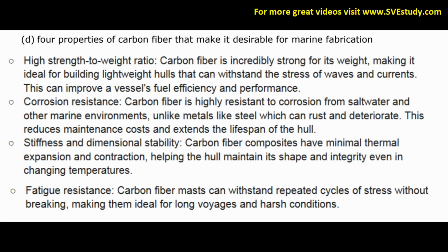D. 4 properties of carbon fiber that make it desirable for marine fabrication. 1. High strength to weight ratio. Carbon fibre is incredibly strong for its weight, making it ideal for building lightweight hulls that can withstand the stress of waves and currents. This can improve a vessel's fuel efficiency and performance.